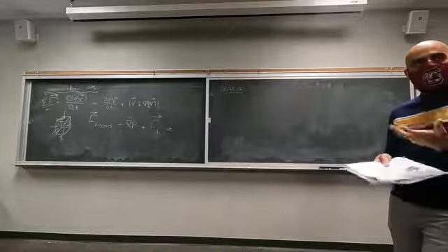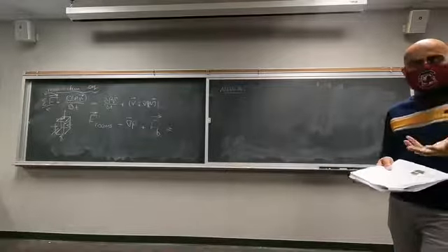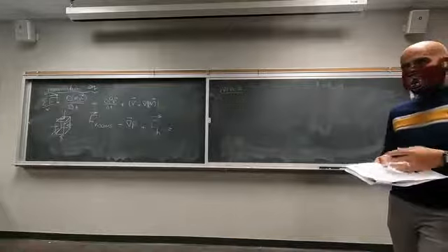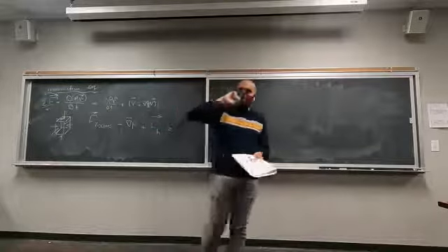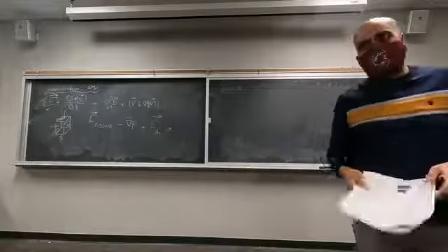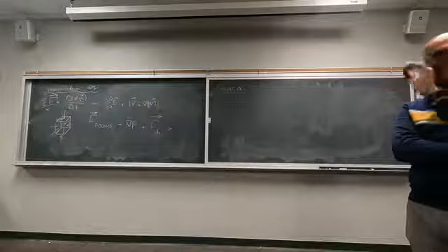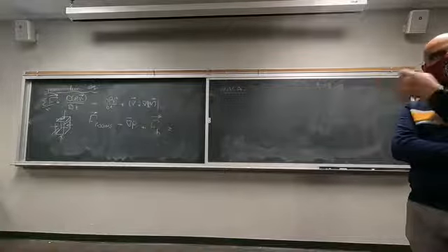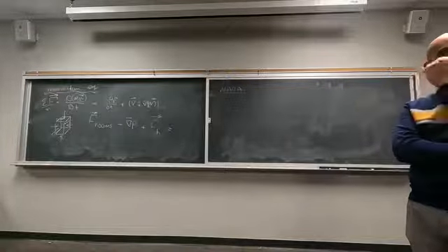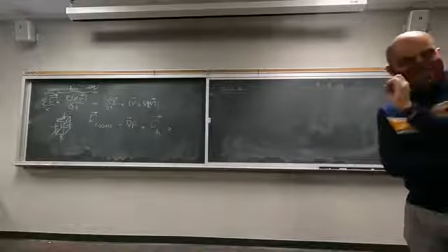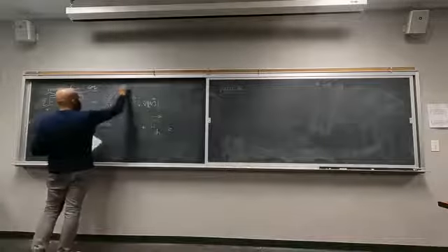The first thing you need to understand is what is the nature of the drag. Drag itself is a force. So to calculate that force, you need to use the momentum equation, right? Sigma F equals ma. So the first thing they did, they ran the wind tunnel, and they let it stabilize, right? They let it become steady. What does it mean? It means that the temporal changes of velocity and temperature are going to be zero. So each point's velocity is going to stay the same. So this part was zero.